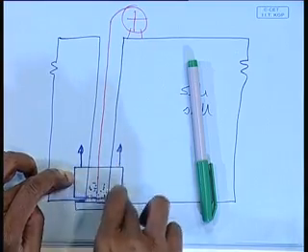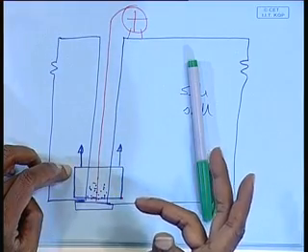First is to synchronize the lifting of this and feeding of the electrode. Second, having these shoes, these pieces, they can be ceramic pieces or can be copper shoes, water cooled, right, which can hold the thing and also withstand the temperature of the molten metal. That means, it will be exposed to around 1500 odd degrees centigrade and should be able to stick to the surface and slide up and not allow leakage of the slag, molten slag or the molten metal. This.